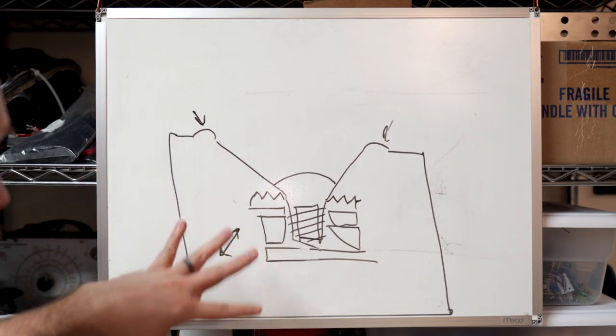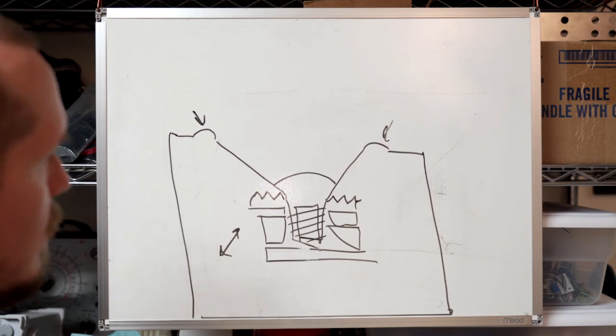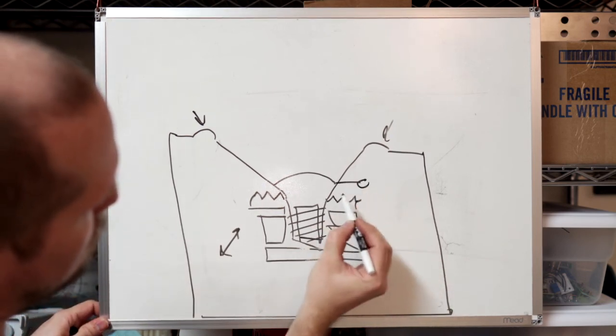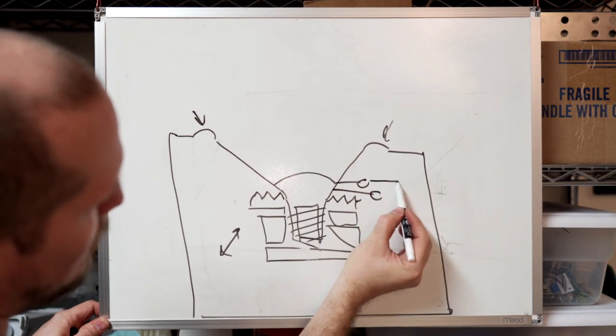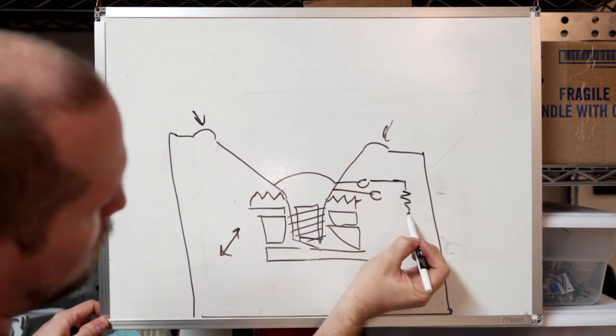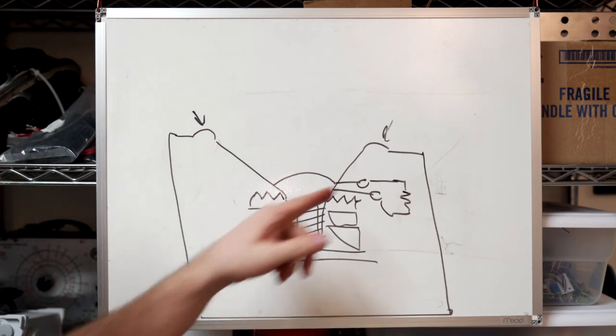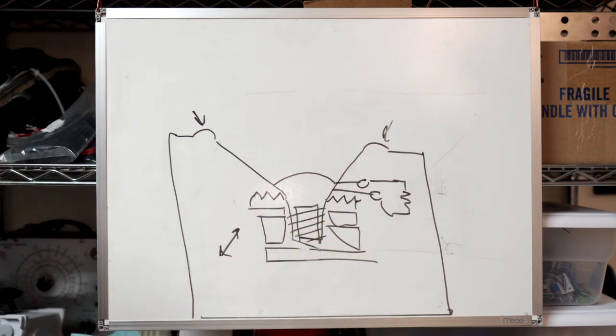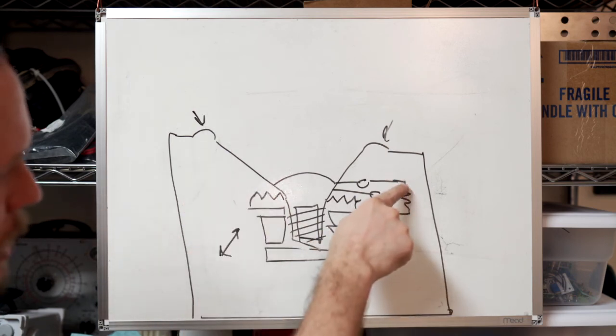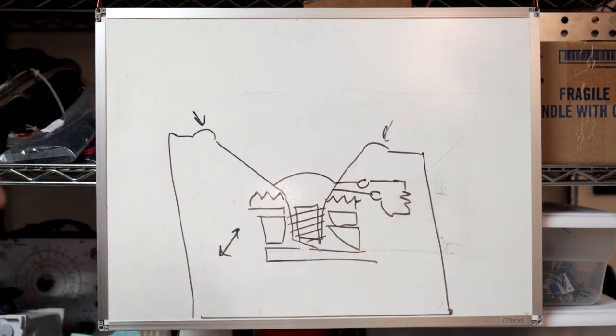And so all those things are dampening, but there's another kind of dampening, and that dampening, as you might expect, is actually the output impedance of your amplifier. And so if the output impedance of your amplifier is high, you're going to have more what's called ringing. The speaker will tend to move at a frequency that it naturally vibrates at after you're done providing it with acoustic energy, and it will ring. And so if you have a low output impedance, it actually soaks up that energy via the magnet coil motor structure.